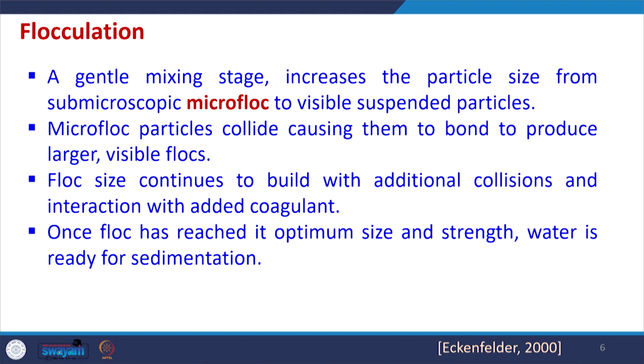So, up to charge neutralization we try to do using the coagulation step. After that we have the flocculation step. It is a gentle mixing stage which increases the particle size from sub microscopic microfloc to visible suspended particles.